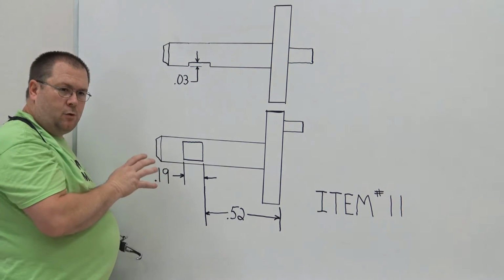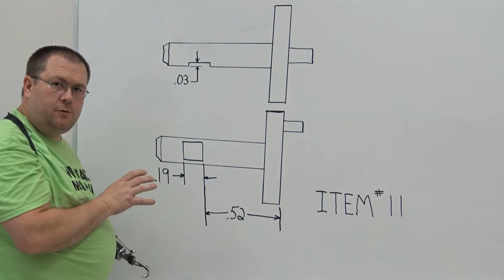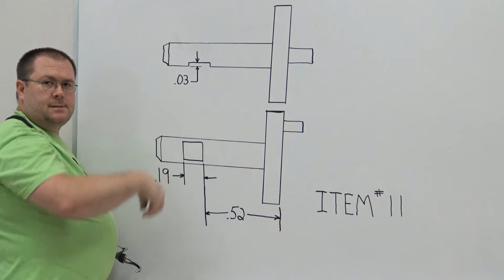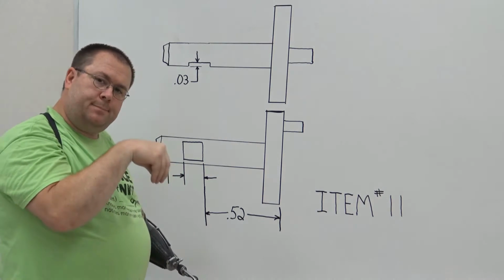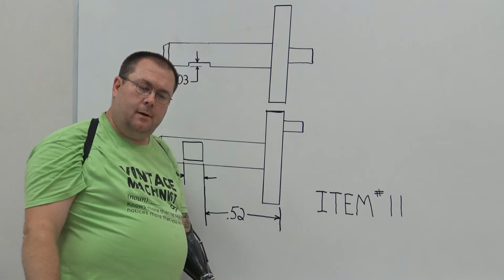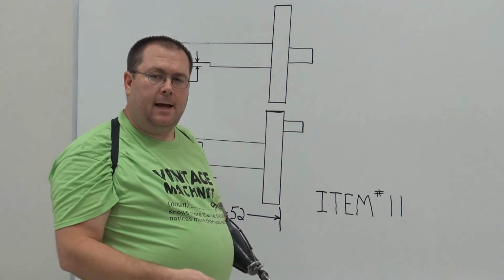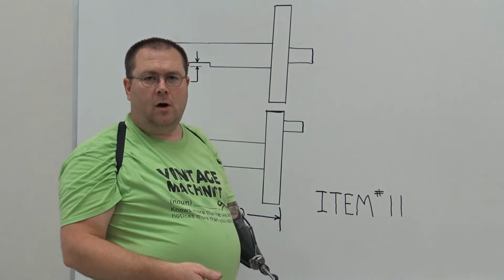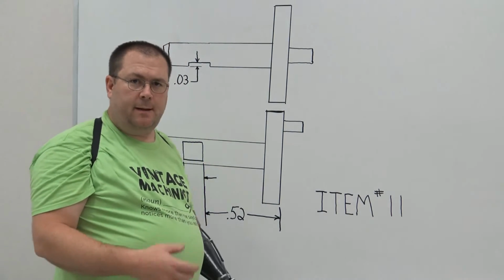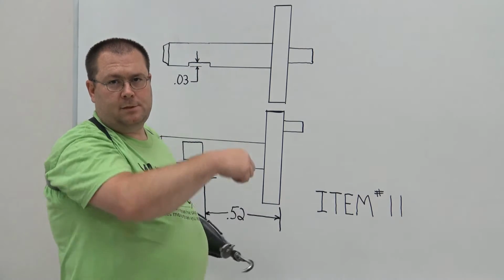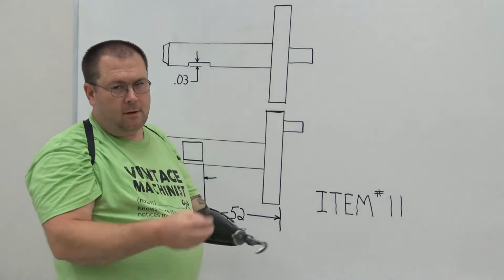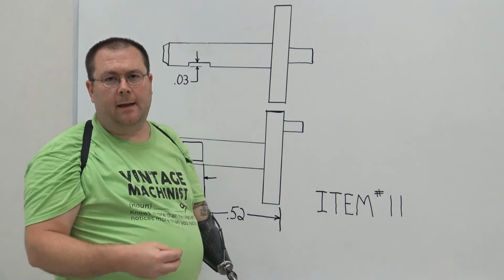This is a different tool, or a variation of the same tool that you've had experience with. The tool that goes inside the spindle that clamps onto your end mill is called a collet. A standard collet size is called an R8 collet. R8 is just a standard that says this size, this shape, with this thread in the back side is called an R8. It's got all different size holes in it, so it'll hold different diameters.